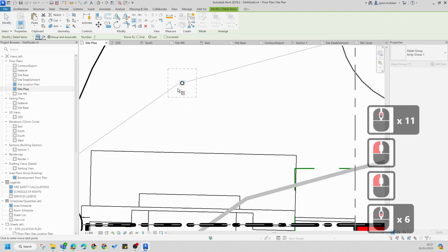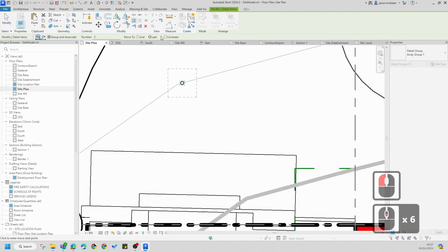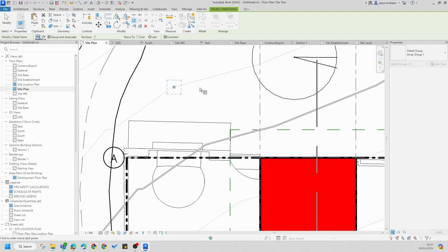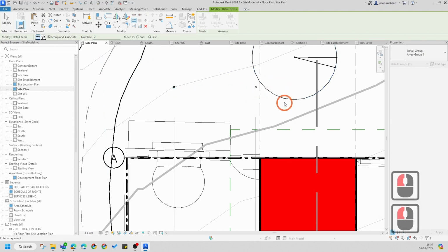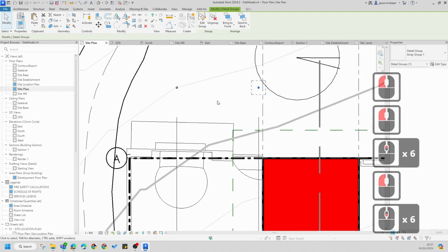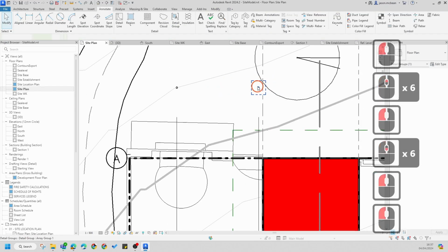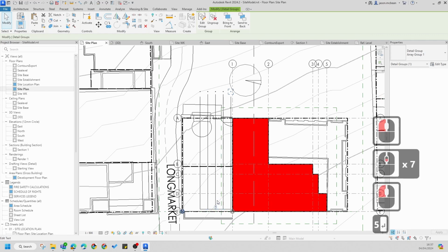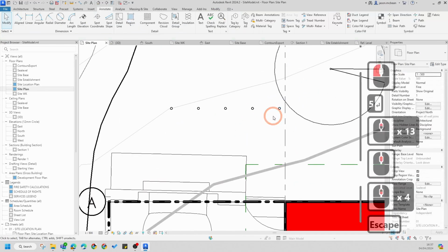I like this function. I'm going to say last, I'm going to say constrain. So I can pick this bollard from there. How many numbers do you want? Last, I'm going to pick one from there to there. Good, so last. Now, if I finish the command, you'd see it gives you this weird dimension. If I say 5 bollards, you'll notice it'll give me 5 bollards in that line.